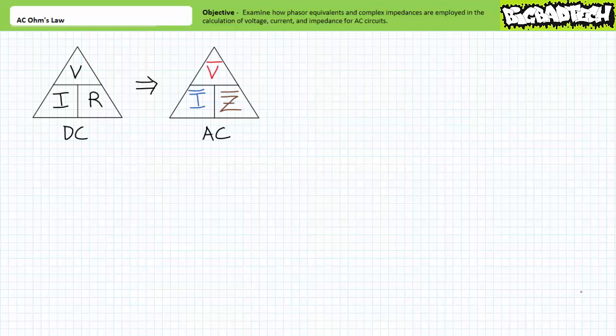And if you've already got an understanding of Ohm's Law as applied to DC circuit analysis scenarios, you'll probably do just fine. The new dimension that using phasors brings to the table for Ohm's Law in AC circuit analysis is magnitude and direction. This implies that the incorporation of reactive elements like capacitors and inductors in AC circuits will include phase-shifted effects that can be accounted for using phasor representation. Allow me to demonstrate. Let's examine the magnitude relationship first, a concept you should be readily familiar with by now.